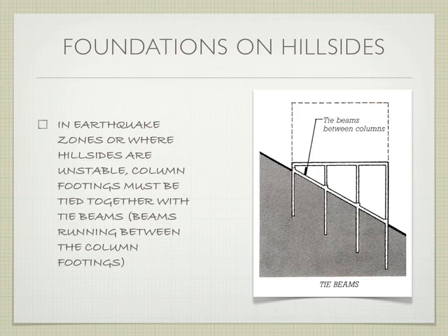So we don't have a footing that goes all the way down or steps down here. We're relying on these column footings, which are very long. They're almost like piles, where we've driven these down in and we're tying them together with a grade beam on the surface of the ground. So instead of having to do all that excavation, we're just drilling really deep holes and we're tying all those together.